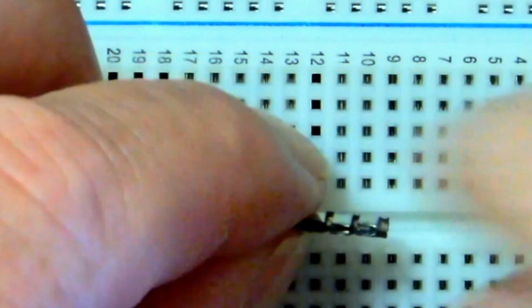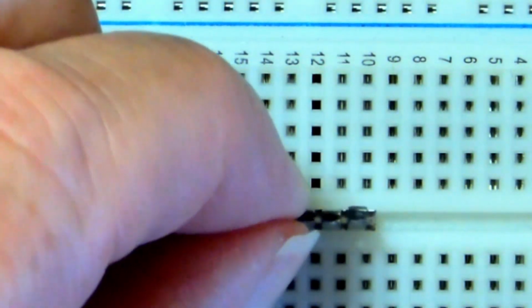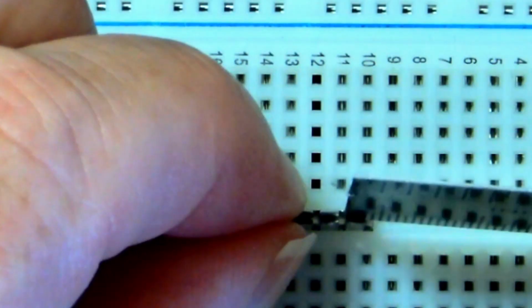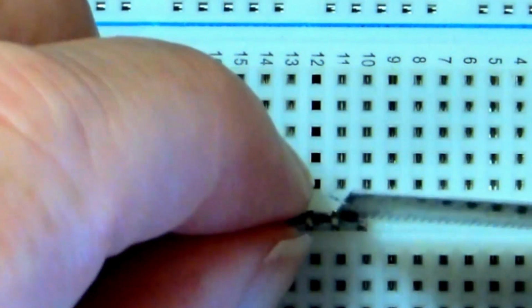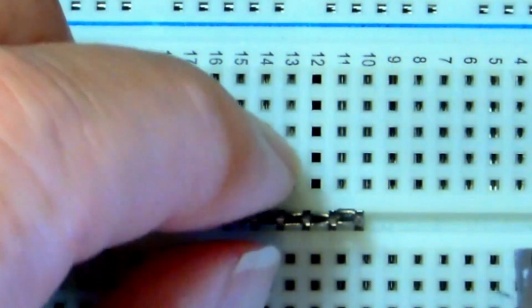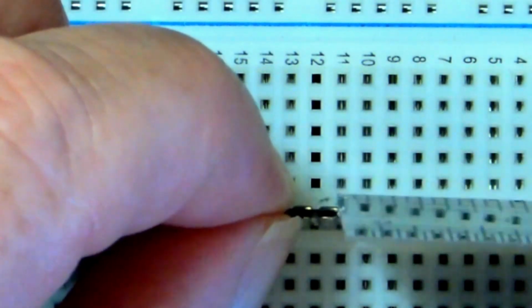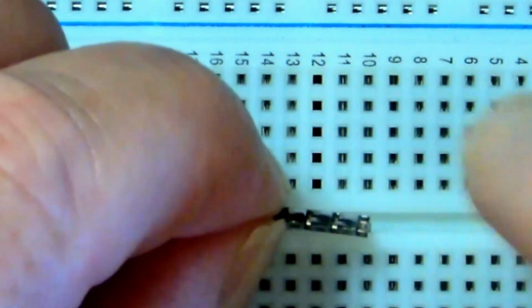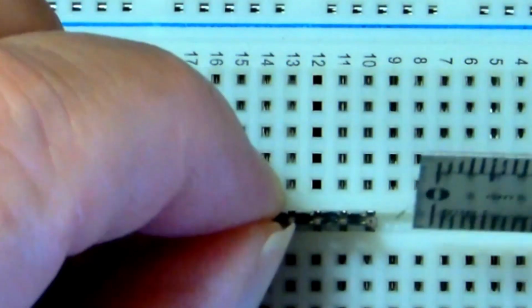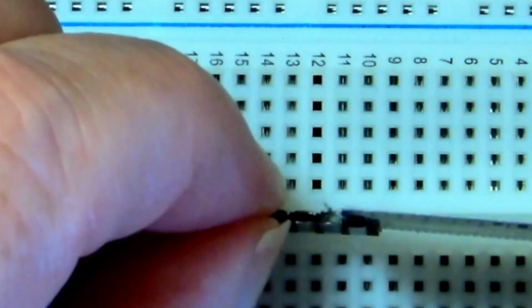So I give it some more, just a little bit more, just a little bit. Right, what happens now? That is definitely open now, and it virtually doesn't slip off exactly, but there's no weight on this connector. As soon as you put some weight on, that's gone. So that's one thing to check for, is to see how elastic those are and how well they spring back. I mean, these are cheap, and it has got a bad rating, so we're kind of expecting this. Really. There's another one which is still virgin in as much as I've not put any wires into it yet.